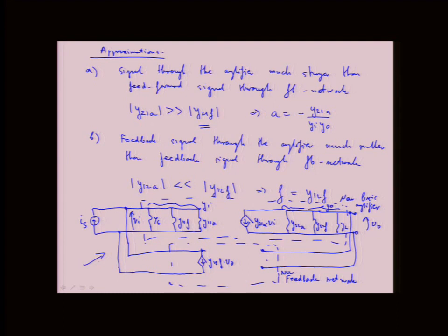When we did the shunt model, we said you don't load the output, so you just measure the voltage, and then you supply the feedback current to the input of the amplifier. And this is exactly what it is. We've now absorbed the loading effects into the amplifier input and output impedances.